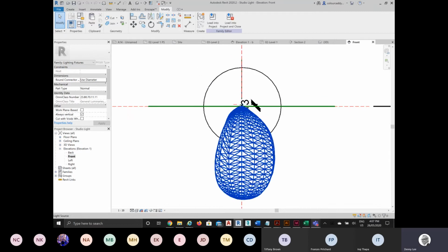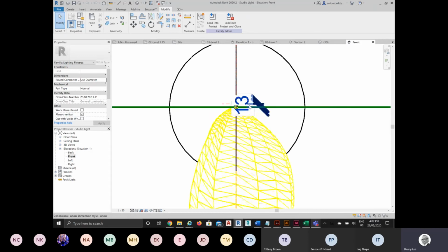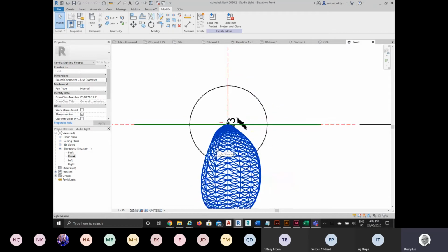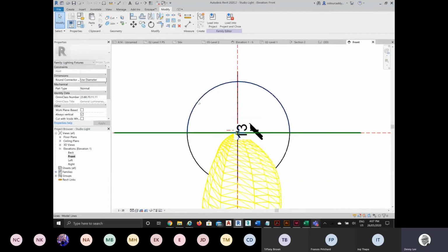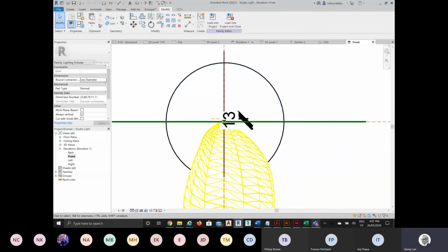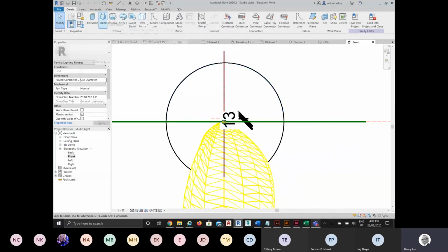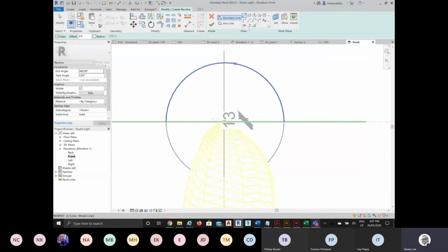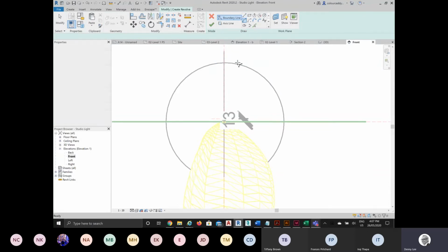Now I'm going to leave it on that distribution, so don't worry about needing to change any settings there. We'll leave that as what's called a web distribution. That's fine. So really all I want to do here is make a light bulb. I'm going to go to create and revolve, and then draw a circle. Oh, sorry, a semicircle. So I'm drawing an arc there.